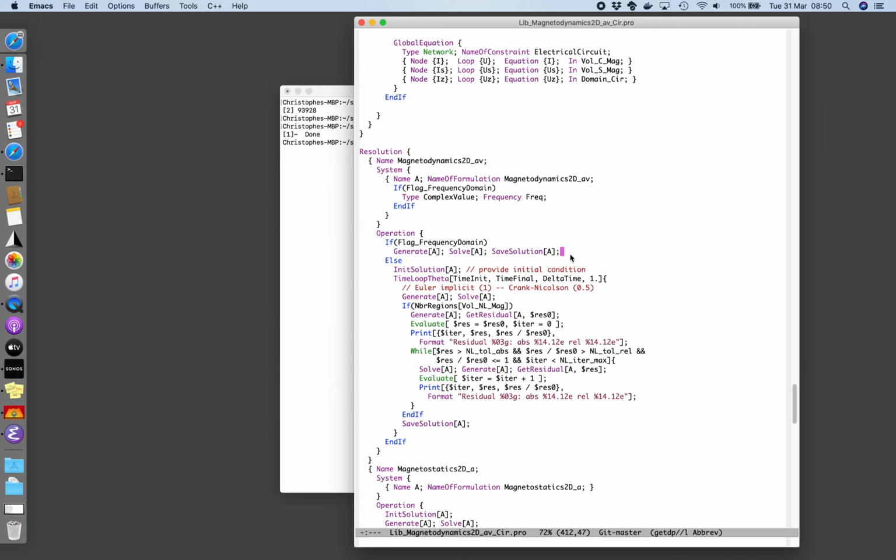And so this would actually allow you to keep magnets, but we are not going to cover that. So you basically write a coupled system of equations that directly exploits a Fourier series of all the fields, and you could keep the DC component and as many harmonics as you want. But in our case, we just keep one harmonic when you work in the frequency domain, and we suppose that everything varies according to this single harmonic. This, of course, is only valid in the linear case, because our assumption is that all the quantities can be written as this simple function of time, which is the real part of this complex exponential, so basically a cosine in time with a variable phase shift.